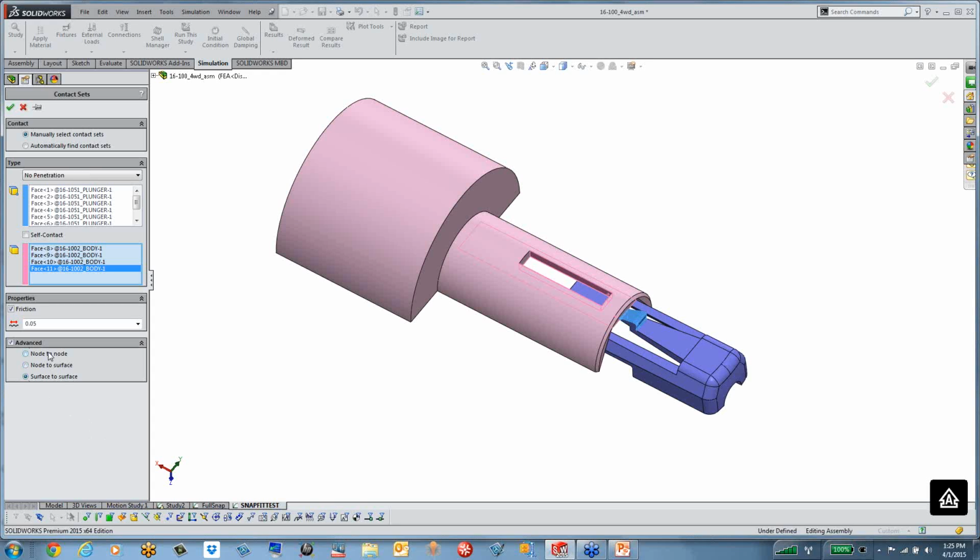All right. So basically, node to node is something where you have two faces touching initially, and those two faces transmit the load only in tension or compression. And so there's no shear load that's going to be transmitted between the two faces. And plus, in this case, what we are assuming is the two faces never can come apart. So they should be always touching each other. Okay. So it's kind of limited, right?